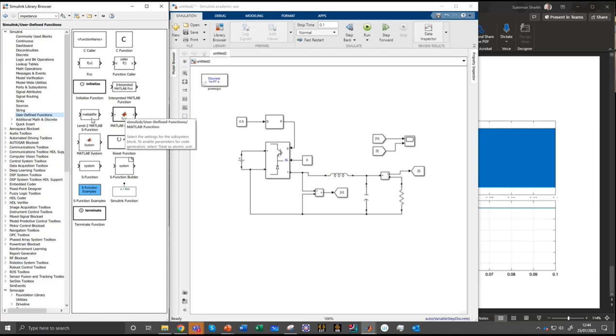So you get a MATLAB function, MATLAB S function, essentially a program in MATLAB, an interpreted MATLAB function. You define in the function the inputs and outputs, and we link it to here. And similarly, you can write within a MATLAB script a call to run a Simulink program and get some variables back.